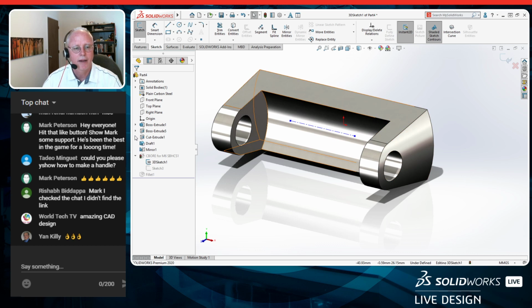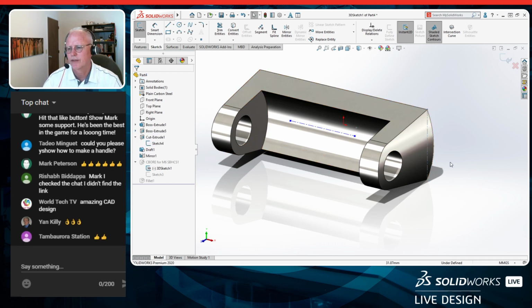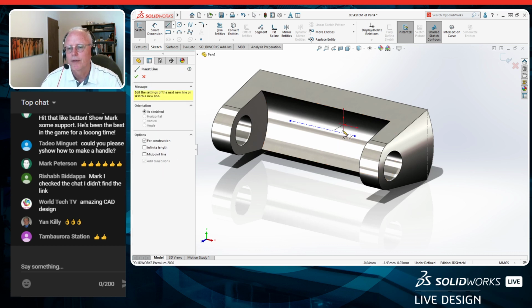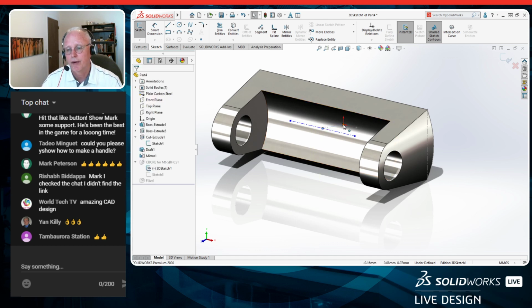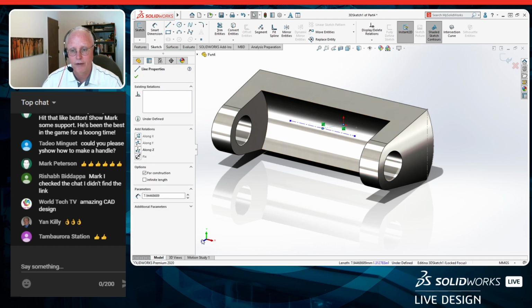I could come back, say, here, show this sketch and try to find a midpoint there and dimension from here to there. Gets a little difficult. Since that is centered, I'm just going to do it very easily. And this captures design intent as well. So I've drawn a line from that origin to the midpoint of this line. And I want this line here to be along Z.